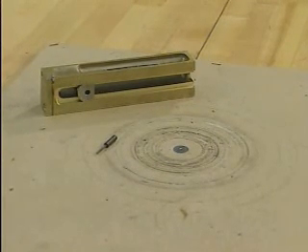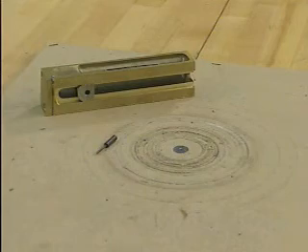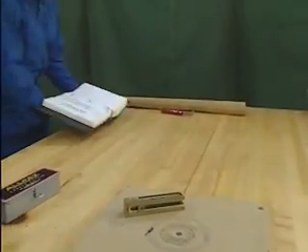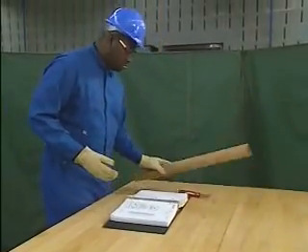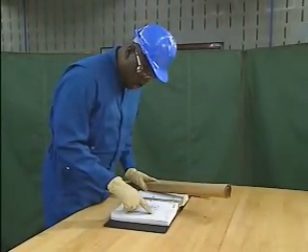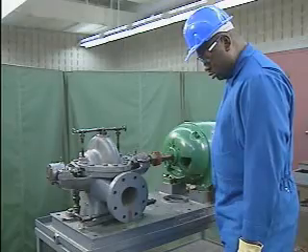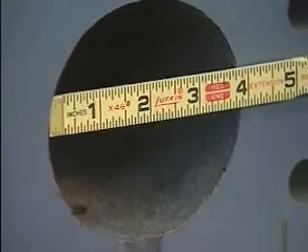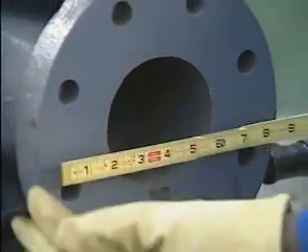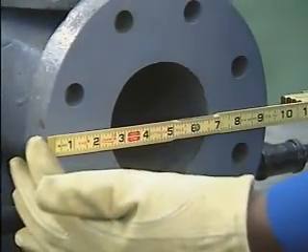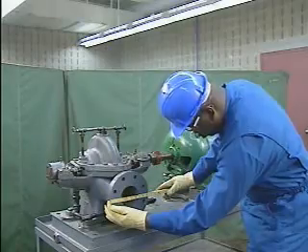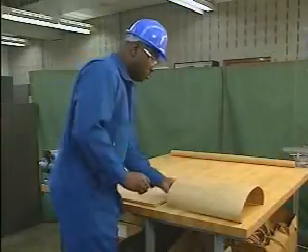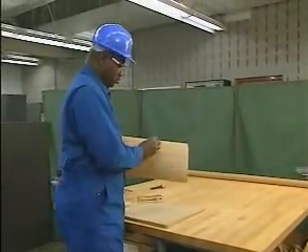Let's watch a mechanic use this gasket cutter to cut a circular gasket to fit a pipe flange. Before he begins, the mechanic verifies that he has the correct gasket material by checking his company's maintenance procedure. To prepare for cutting the gasket, the mechanic measures the inside diameter of the flange and the outside diameter of the flange. These measurements will allow him to set the blade on the cutter to cut a gasket that will fit the flange exactly.